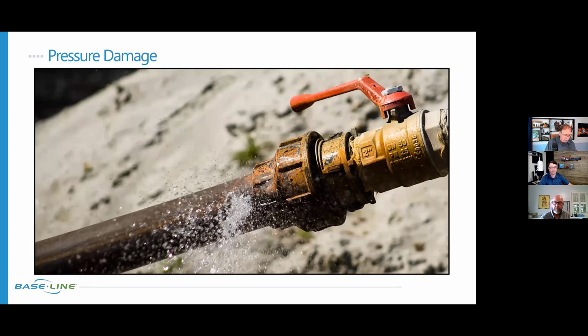Pressure damage is something that we could use pressure components to address. So water hammer damages fittings, it breaks pipes. And if it's bad in a 2-inch pipe, it's going to be catastrophic when we get to a 6-inch pipe. You think about the hole that's going to create if we have a broken 6-inch pipe. So surges or spikes in water pressure are going to make that water hammer even worse.